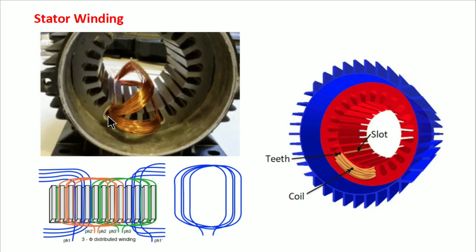So as we have already discussed, for the one phase coil, you can see here there are three sets of coil of yellow color, in one slot 2, 3, and the other end goes at 180 degree electrical, and then the next coil of the set in the next slot.